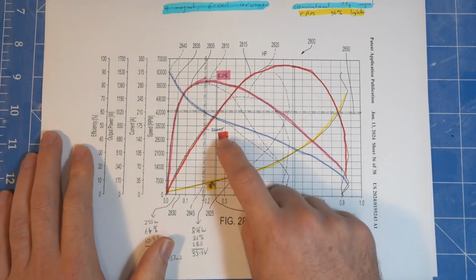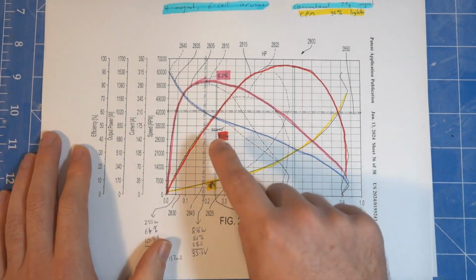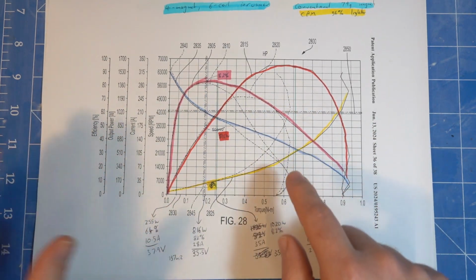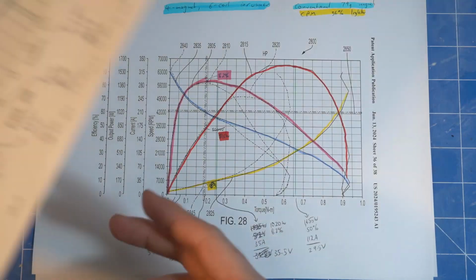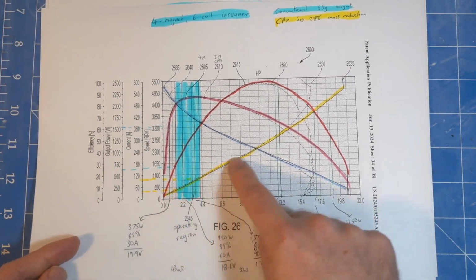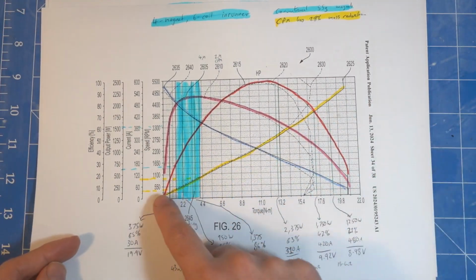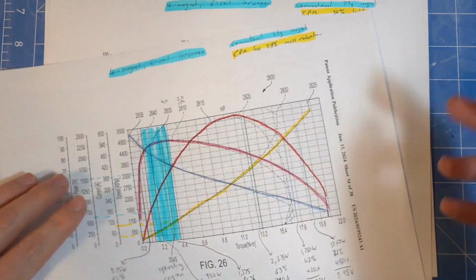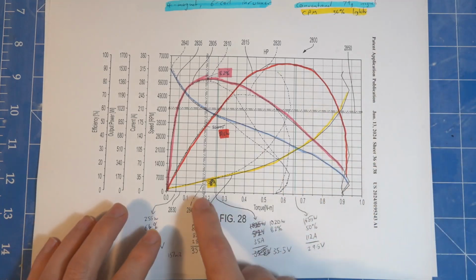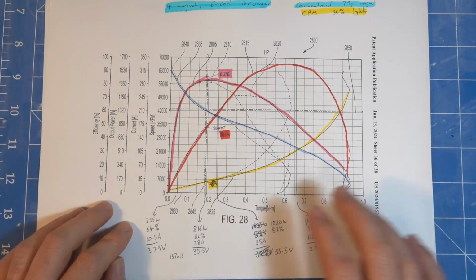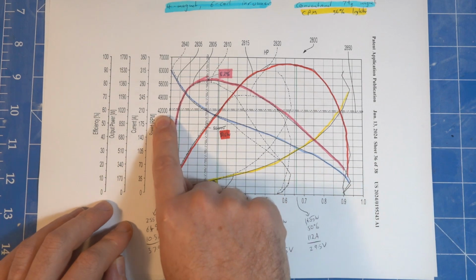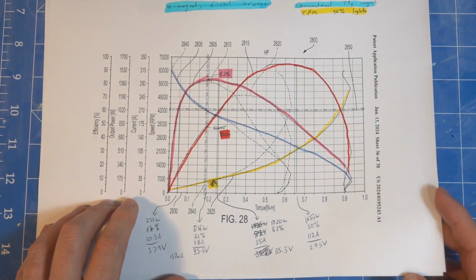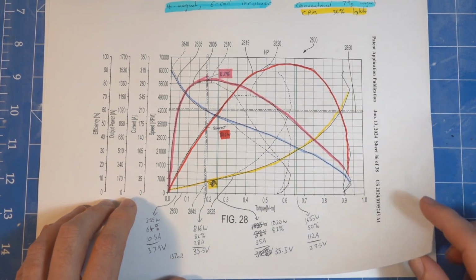At its operating point, it's 816 watts, 28 amps, and about 82% efficiency. The current is quite non-linear in this one. This one here, relatively linear, because that's what a current versus torque should be, linear. Mostly linear. Obviously, as things heat up, it gets worse, but this one goes very non-linear. But yeah, 42,000 RPM, quite high for a vacuum or fan, or blower, sorry. I don't know if they're doing any gearing down or if that's just how fast they're running it.